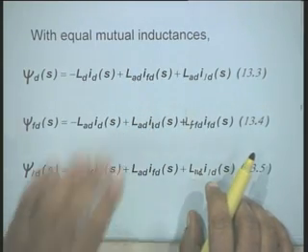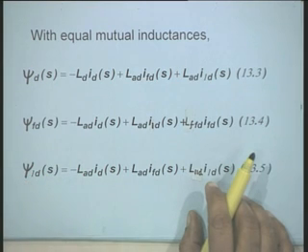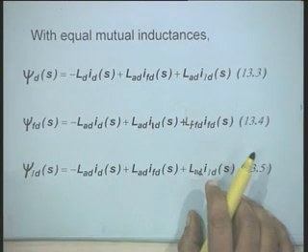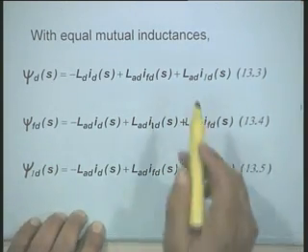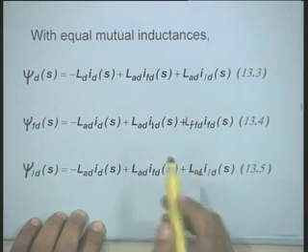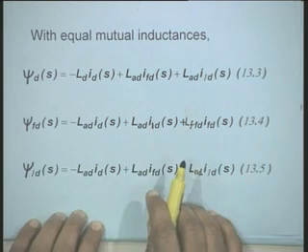Here, while writing the equations, I am considering one damper on the direct axis. Therefore, we were denoting the damper winding by the symbol K d; K used to stand for the number associated with the damper winding. Since K is 1 in this case, it becomes L 1 d. Further, we are assuming that all mutual inductances are the same, so that this L A d appears in both terms.